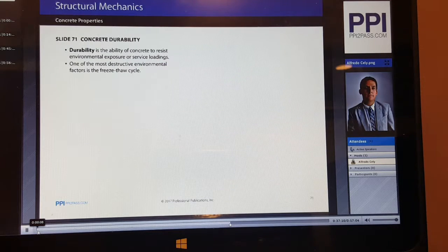And when those steel bars start to corrode, they start losing their tension capability, their ability to withstand tension. So then we go into this vicious cycle. We start losing more tension, the concrete starts to crack and spall more, then we get to a point where that cracking and spalling is starting to impact the compressive strength of the concrete, and then at the end even reinforced concrete can fail.